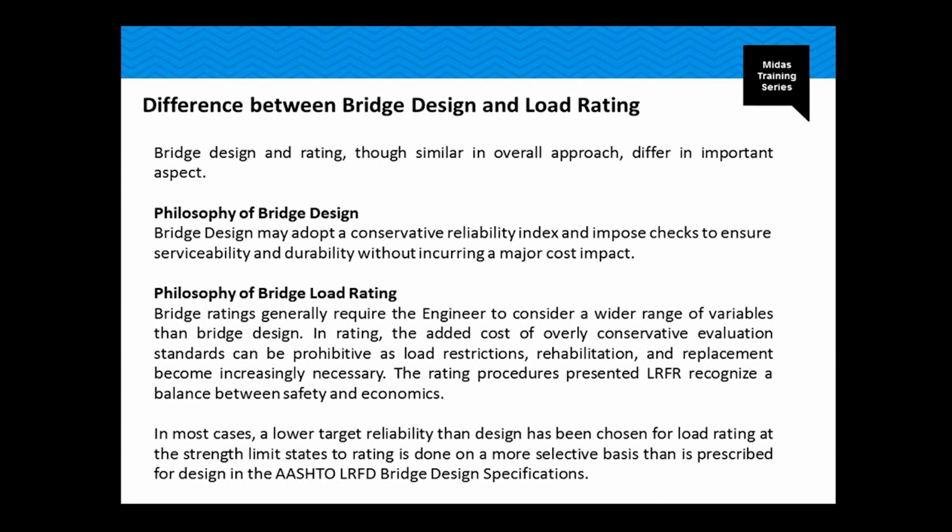The rating procedures presented in the LRFR, which is the code that we're going to go over today, recognize a balance between safety and economics. In most cases, a lower target reliability than design has been chosen for load rating. The strength limit state rating is done on a more selective basis than is prescribed for the AASHTO LRFD bridge design specifications.